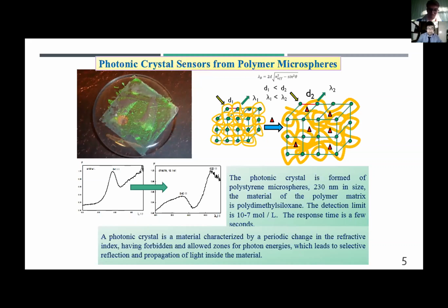The resulting samples were numbered and weighed. The quality criteria were good adhesion to the substrate, uniformity of color and thickness of the crystal, and the absence of significant defects at the macro level. Since the resulting polystyrene microspheres will be used in the future to create sensors with an optical response to external influences, one of the most important product parameters will be a narrow particle size distribution.